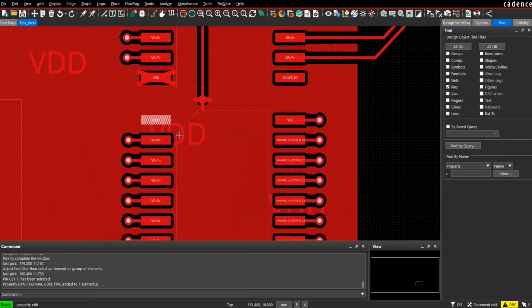then we see what is happening here. We see this pin is now connected in a full contact fashion to the plane. And this is now coming from the property, which is overwriting all the other settings: the settings coming from the global dynamic parameters, from the layer dynamic parameters, and also from the instance parameters, which I didn't show here now.